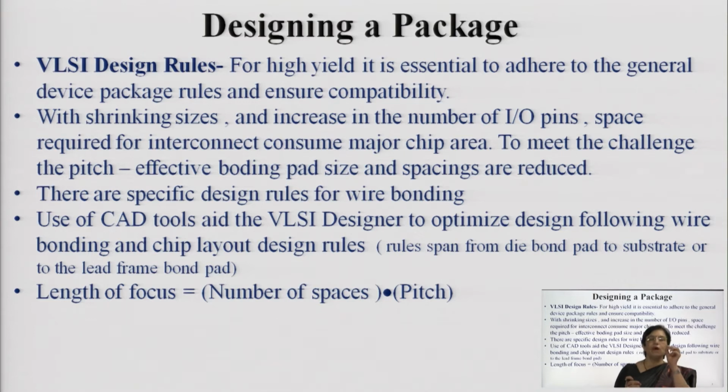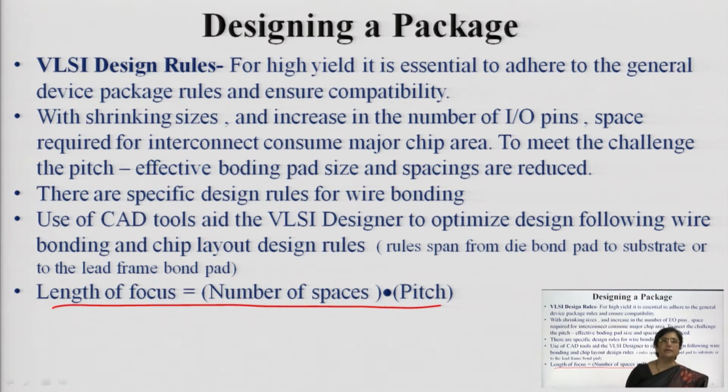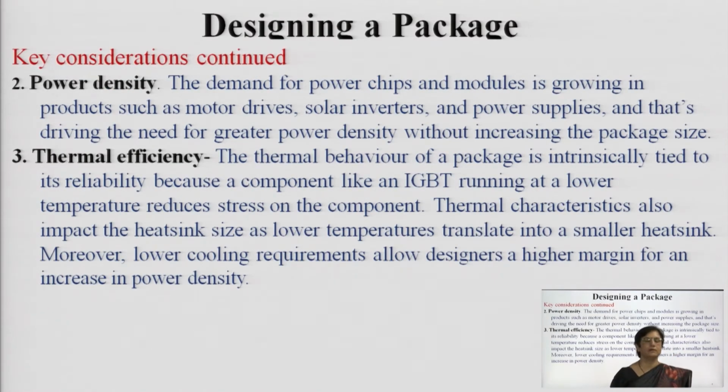So, if you have n pins, there will be n minus 1 spaces, and the spacing, the separation between them, decides the total dimension of the chip, and this is what is being exhibited over here. Another concept you need to consider while designing is the power density.